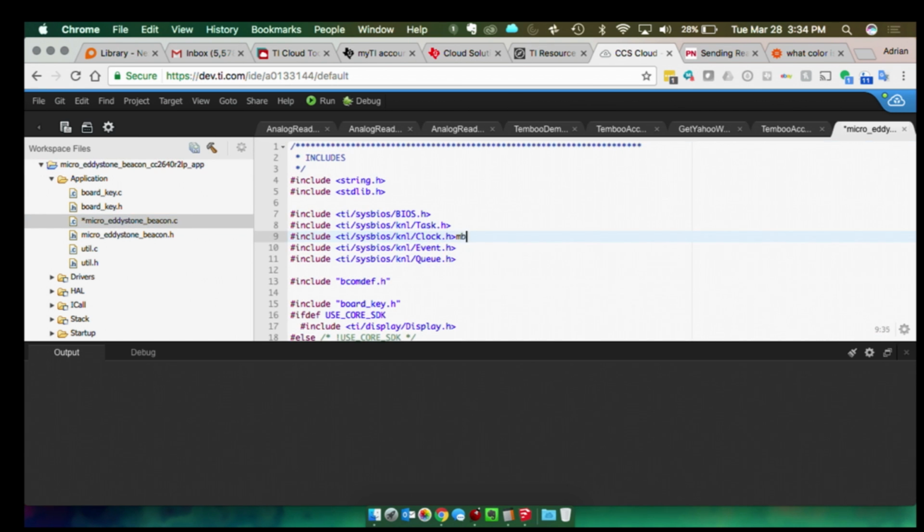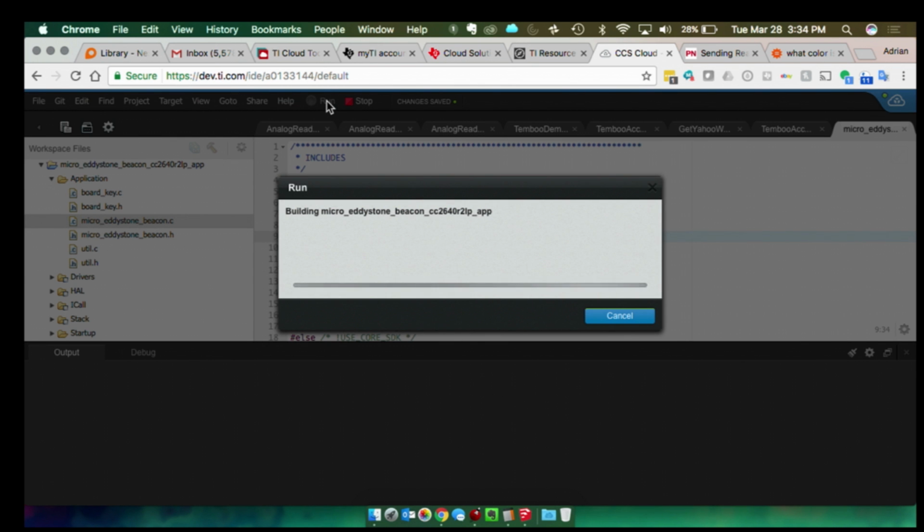And you can actually modify this code, right? So this is all open source software that you can start developing. Hit the run button, that'll compile the code and ultimately flash your hardware. So if you actually plug your Launchpad over USB, take advantage of our compiler in the cloud, compiles your code, generates a binary for you, sends it back, and flashes your hardware over USB. And this is all free, right? You don't have to worry about licenses for the environment.